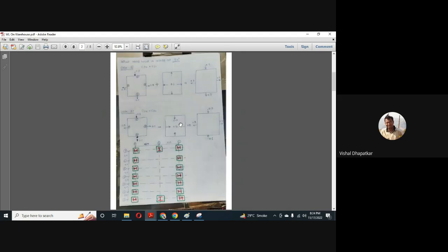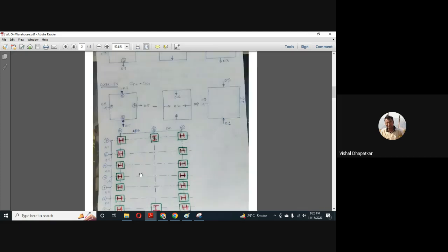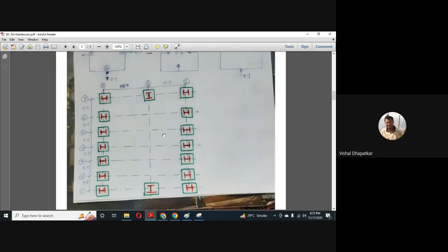So this is how we calculate the total force coefficient. Then we have to apply the total wind load on these steel columns based on their contributory width. Okay. So first, for wind load on columns, our span is 5 meters between column centers, and 6 meters on the gable end columns.